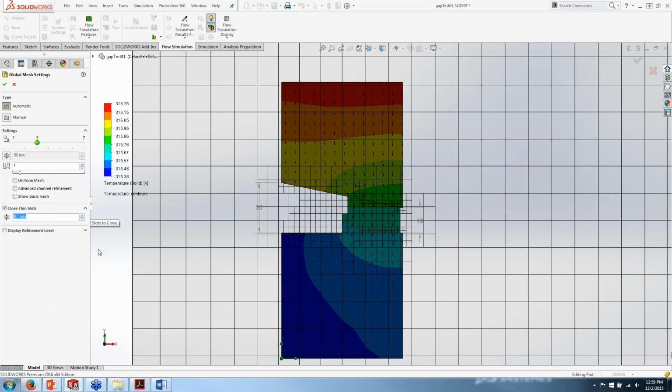Now, what this tool is not used for, surprisingly. You do not use this if you want to run an internal study and you have leaks. This does not close leaks. So I'm sort of differentiating a bit between a gap and a leak here. Okay, this will not close leaks. Okay, maybe in the near future it might be able to. Okay, I can definitely see some enhancement ability for this, but currently it does not.